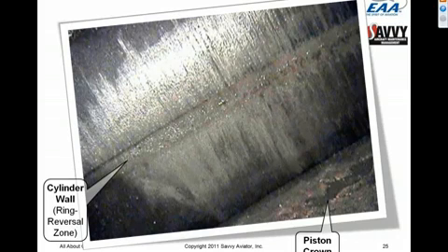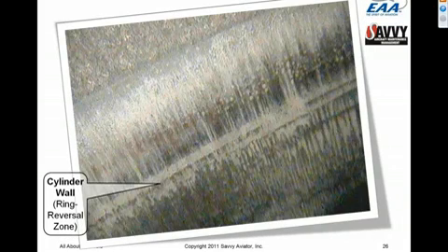Here's a picture of a different spot on that same cylinder barrel, and you can see what bad condition the cylinder barrel is in. So it's really quite amazing the kind of images we can get with a borescope, and how we can tell exactly what the condition of a cylinder is, instead of just getting a rough approximation, which is all the compression test gives us.